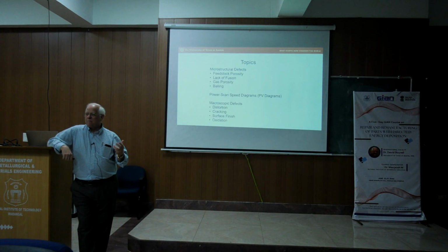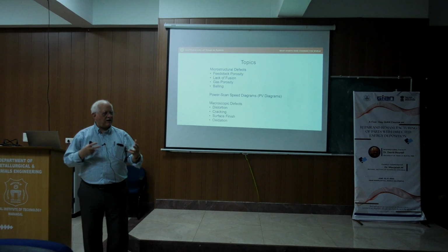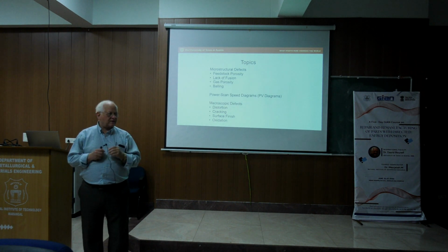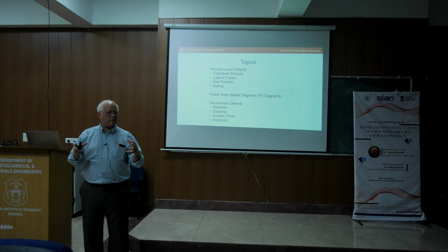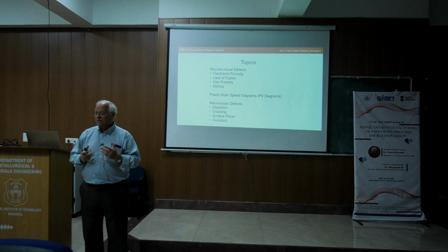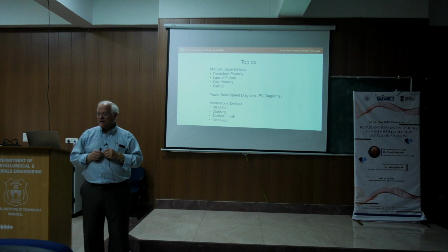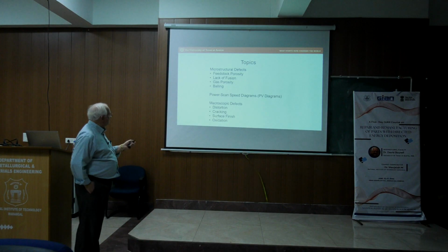It turns out that that porosity has been in the powder all along, but the powder processing people don't care because they do all this sintering and pressing of the powder that removes it. In this case, all we're doing is a quick melt and resolidification of the powder, and often there's not enough time for that porosity to escape, and so it's captured in the part. So that's what the feedstock porosity is.